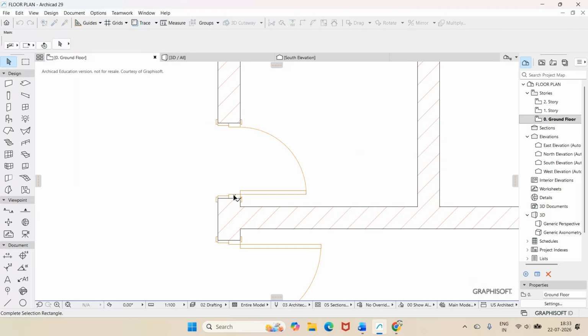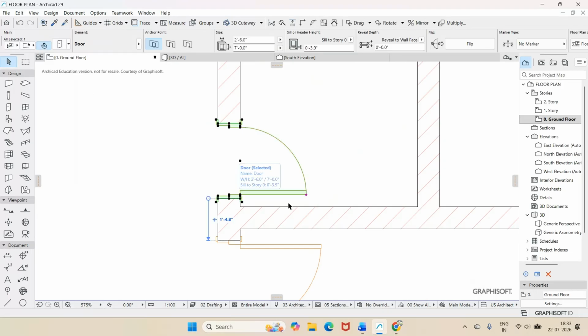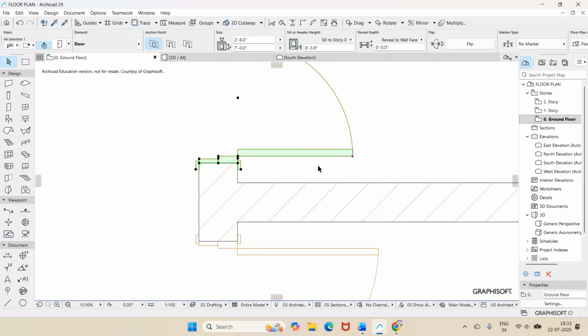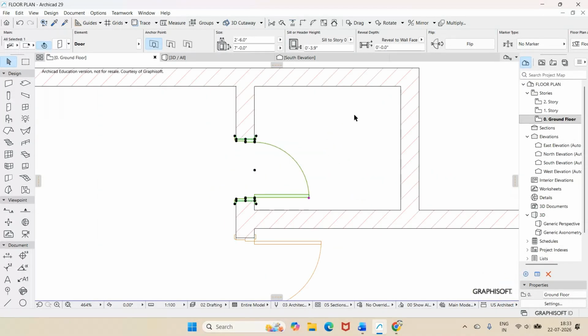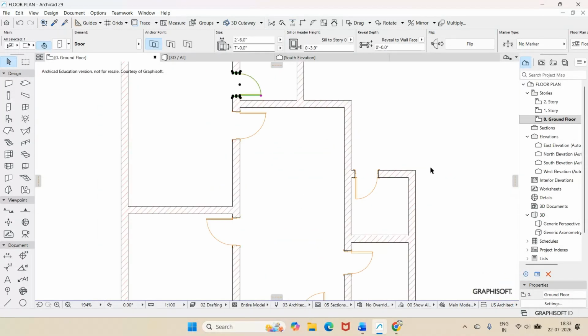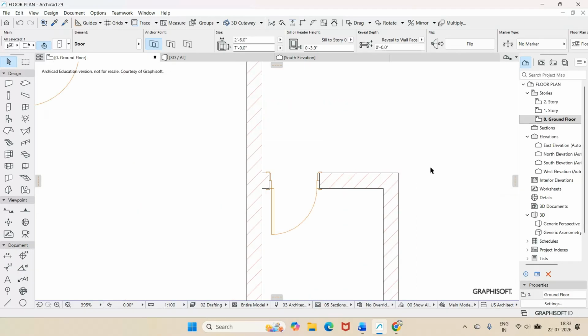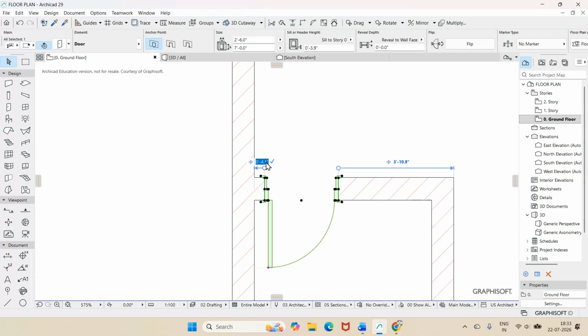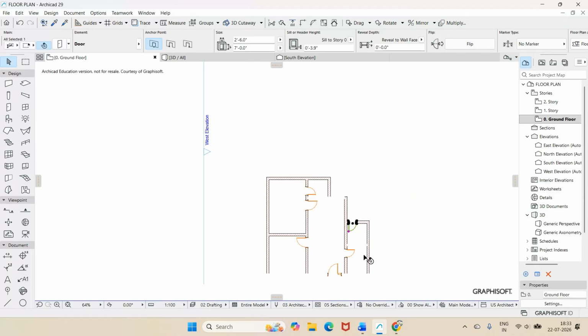Sorry, you just go to quick dimension. Now you want to take this dimension from here to here. Then you change this dimension to 4.5 inches. So similarly, I want to keep it under this. Go to selection of this. Then you give 4.5 inches. And similarly on this side.